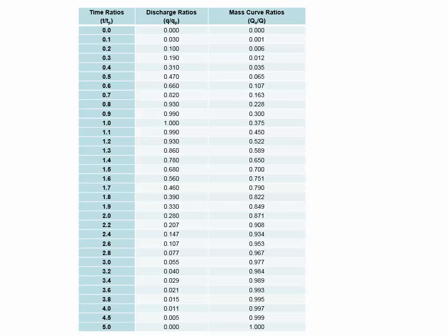So what that means is at t equals 87 minutes, what's the ratio of t versus t sub p? 87 minutes divided by 60 to convert it into hours is about 1.45 hours, divided by our time to peak of 0.729 hours.